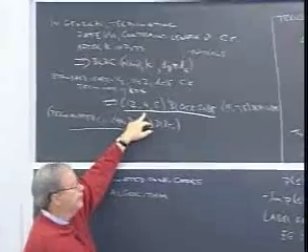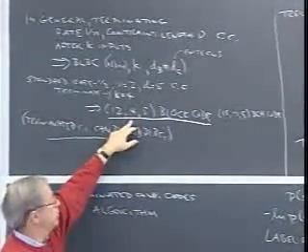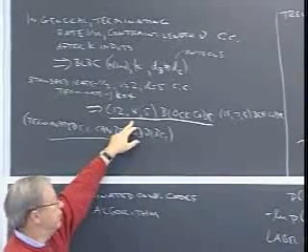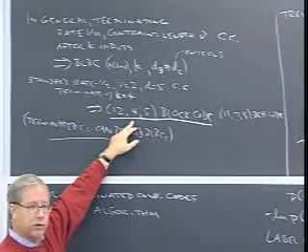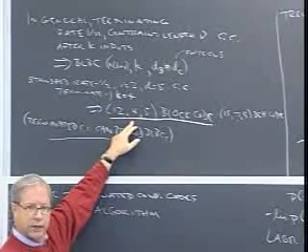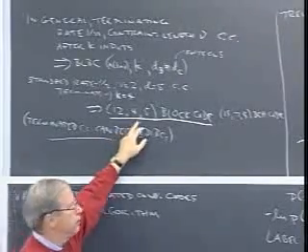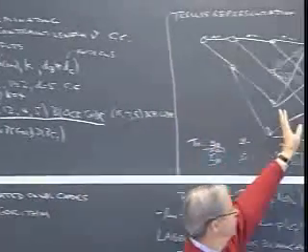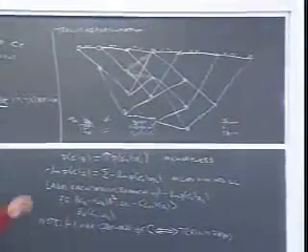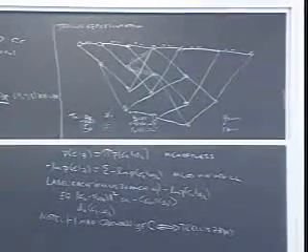All right. So now what is maximum likelihood decoding? I want to find the one of those 16 words that has the greatest likelihood or the least negative log likelihood over all of these 12 received symbols, or 6 received times.